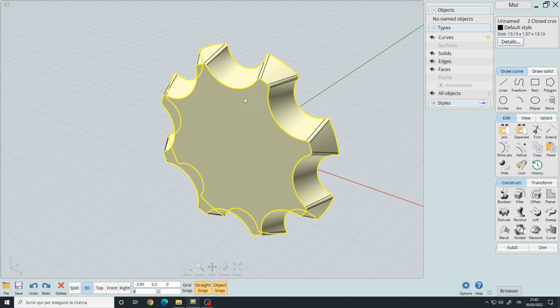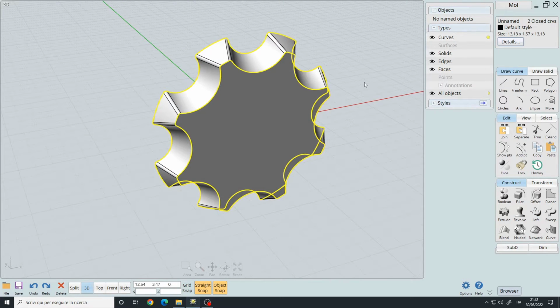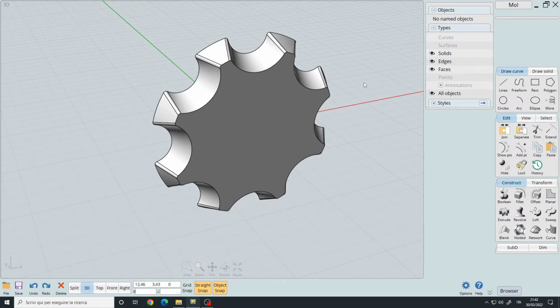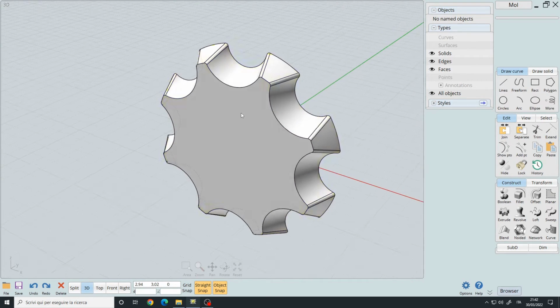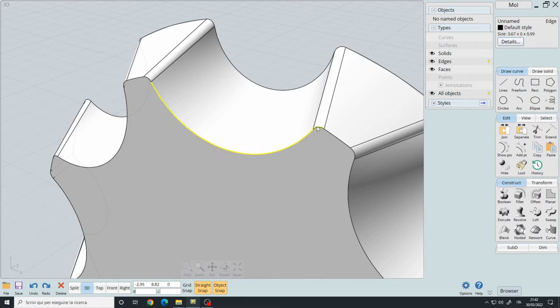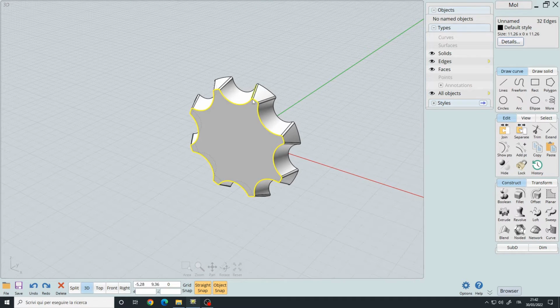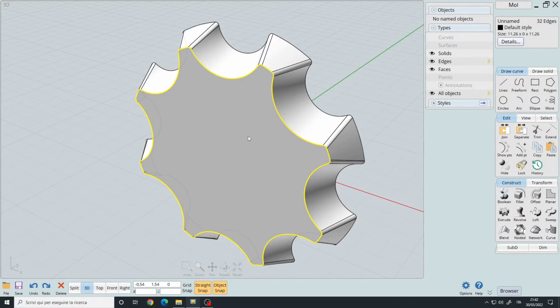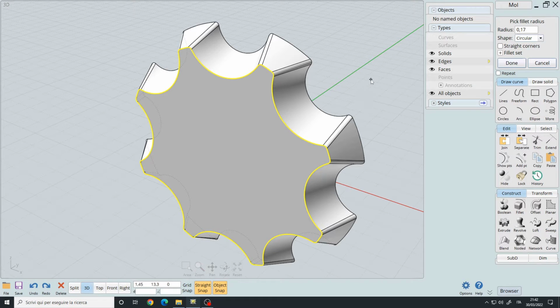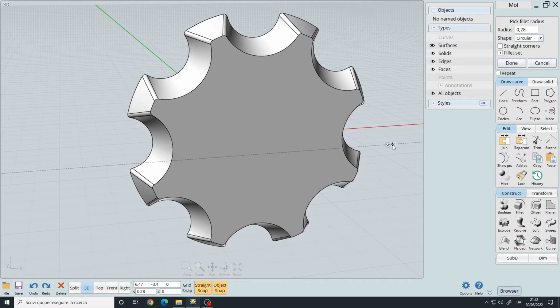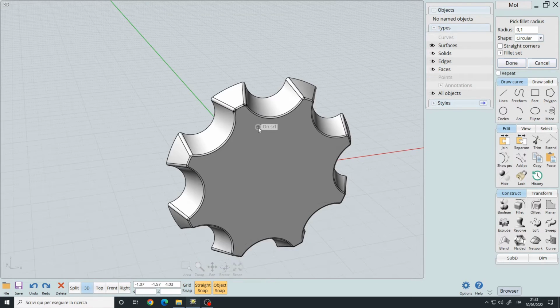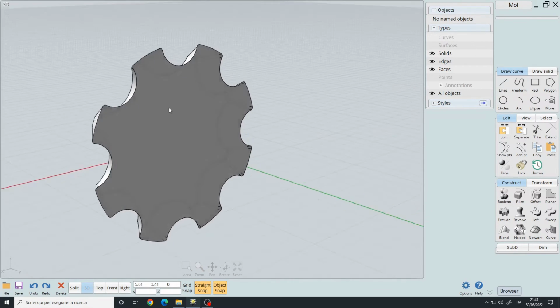And then press the down key or right click, and we can delete the curves by using the delete key. Okay, we have this nice looking metal piece. Can add maybe more bevels. I will select this first edge, the next one, and then press Alt A to select the whole loop. This is a custom script. Then press Ctrl B and let's select a radius 0.1, and this is perfect. Right click to confirm.